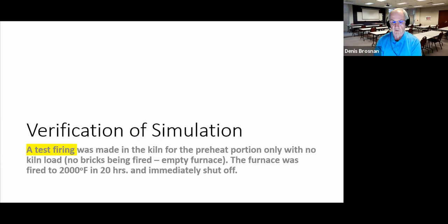So with one class, I decided we're going to go out in the laboratory and we're going to actually operate the Swindell kiln. Okay, we're not going to go through an entire cycle because we didn't want to waste the natural gas, but we did a test firing. It was made in the kiln, only in the preheat portion of the kiln with no kiln load. No bricks were being fired. It was an empty furnace. And the furnace was fired to 2000 degrees Fahrenheit in 20 hours and immediately shut off.